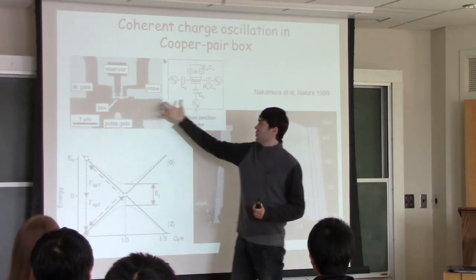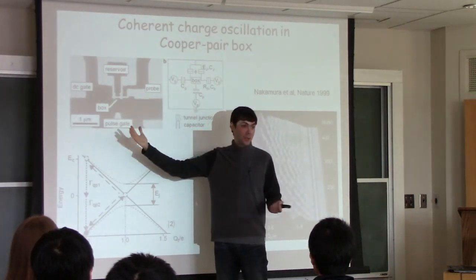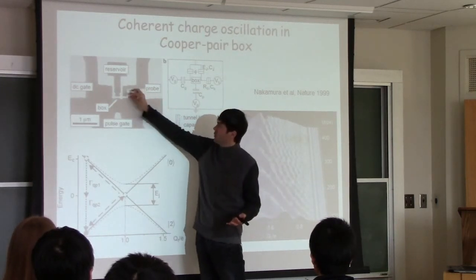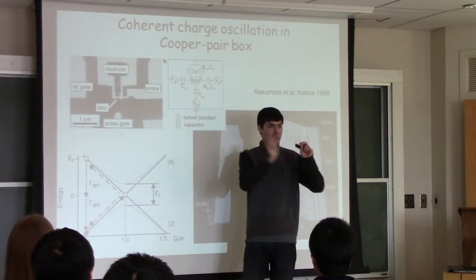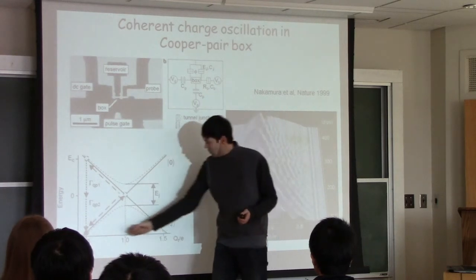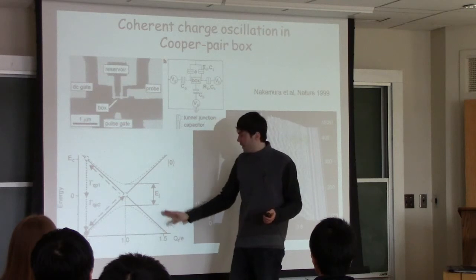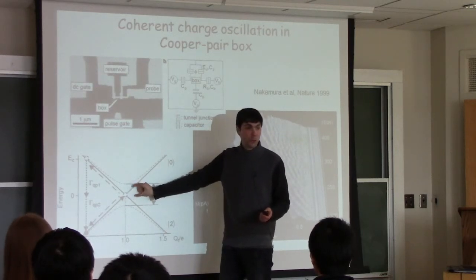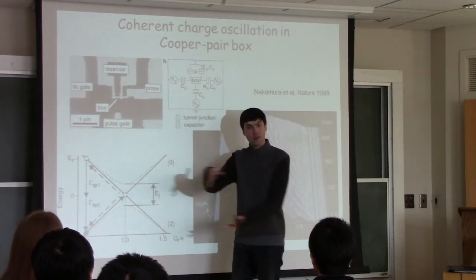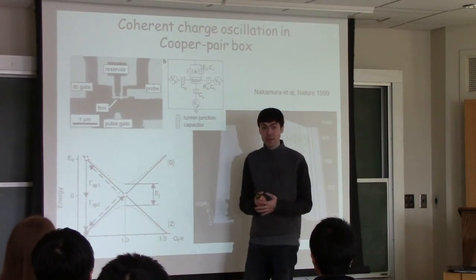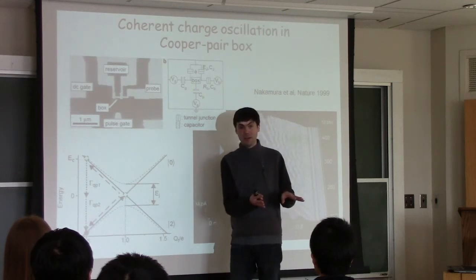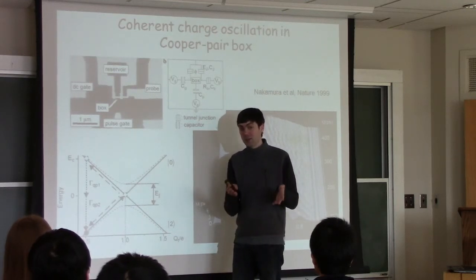And this circuit is built on a substrate, which is a piece of semiconductor, which has a bunch of charges in it. Charges can live on the surfaces of these metals, and any charge jumps around this circuit immediately translate into decoherence, because it shifts you along this axis and changes the gap, the separation between the levels. So it changes the coupling rate, the precession rate, and leads to dephasing that you observe. And charge noise is, in general, the worst noise of all. So it's not that the coupling is stronger or weaker, it's just that charge noise is the hardest to suppress.